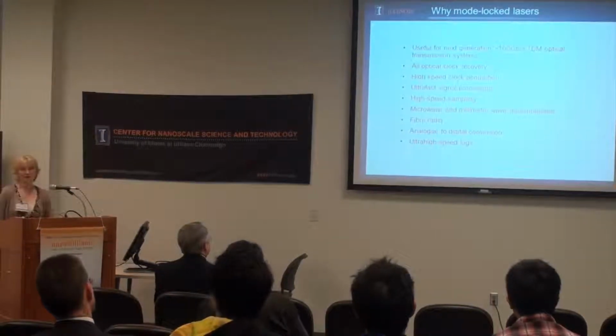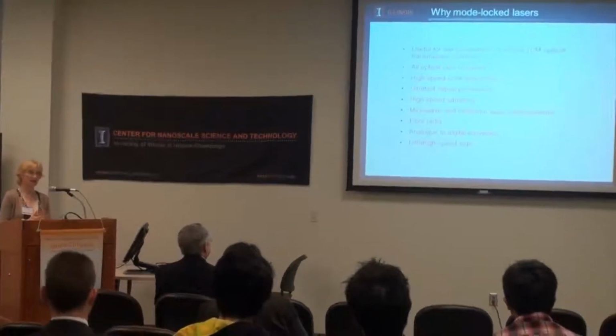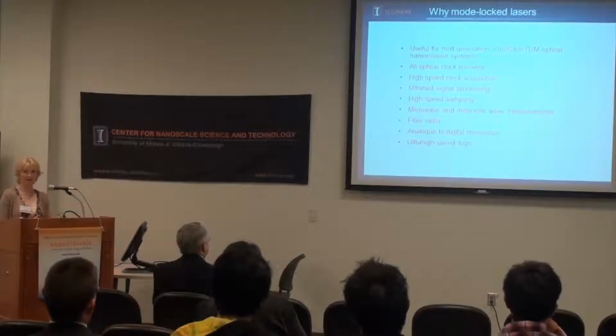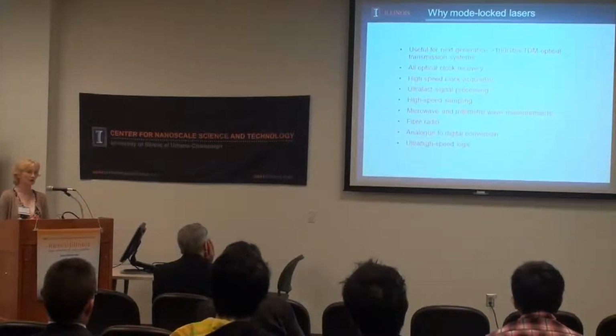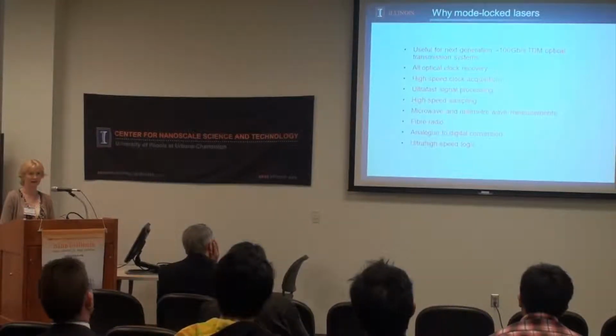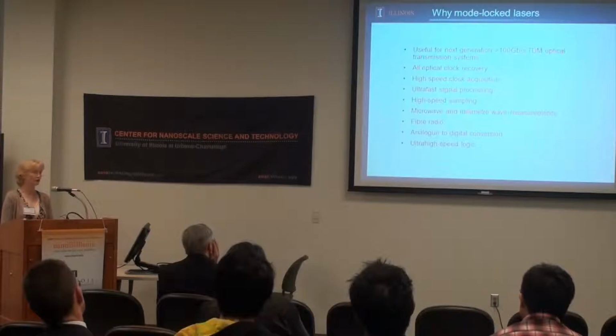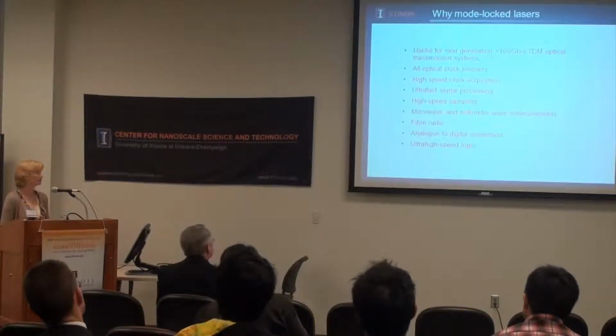Right, mode-locked lasers are basically used in applications where you're looking for short pulses, particularly at high frequencies. Semiconductor lasers mode-lock most easily at tens to about 100 gigahertz, and that's related to the length of the cavity. That's the pulse round trip time. Bigger lasers give out more power and operate at much lower frequencies, down to the megahertz range.